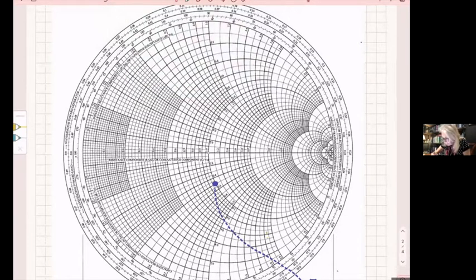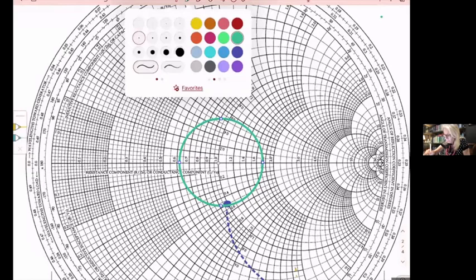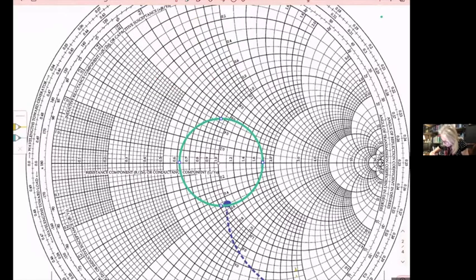There is going to be this one, whatever has its center at the center of the Smith chart and goes through this point, the point of my admittance, there. And from the admittance, I have to draw the diameter of the circle that will go like this.